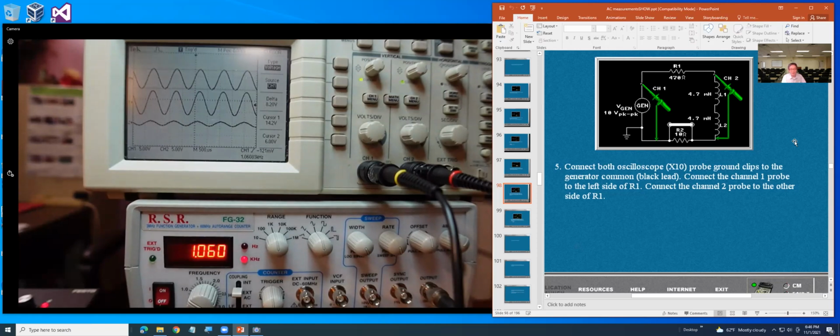That is normally when you're working, you must set that up before you can do. Okay, so this is how you measure the voltage without ground. That means R1 left side, R1 right side, they're not connected to the ground at all. Then you must be using channel 1 minus channel 2. Okay, any question on that one?